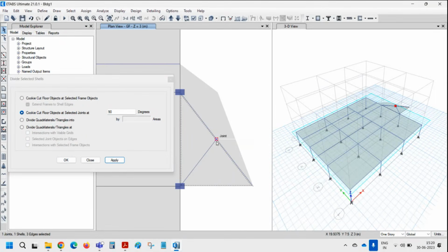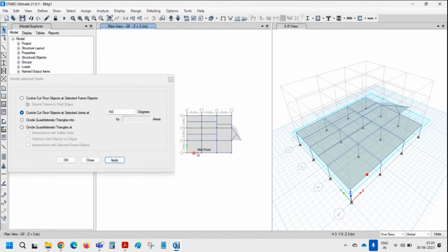Say this object. Some angle, let's say 35, 60. You can see the cut. So the orientation for the angles, if you look at this, this is the plan view, right? X, this is 0, anti-clockwise are positive. So 90 is Y, 180 is negative X, 270 is negative Y, 360.